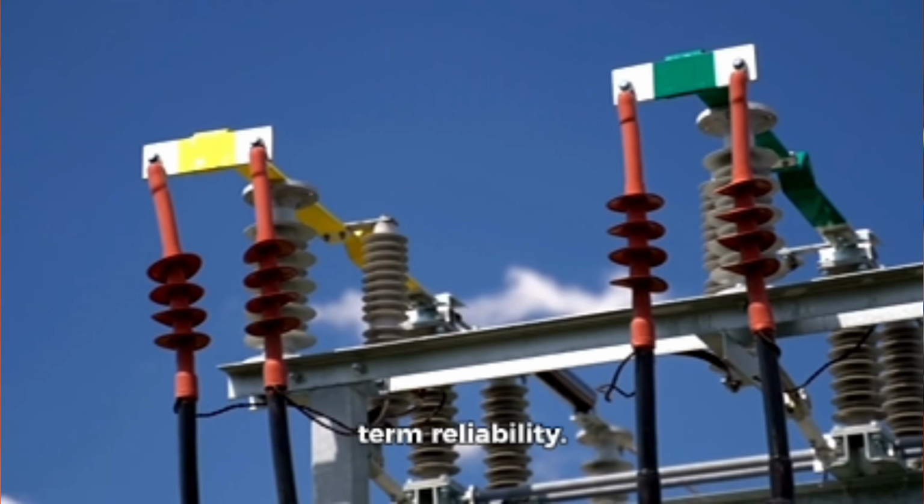Now let's focus on selecting the right MCCB, the Molded Case Circuit Breaker, which will be installed in the main distribution panel or meter board. This is one of the most critical components in the electrical system as it provides protection against overloads and short circuits. To choose the appropriate MCCB, we first need to determine the total load and current.